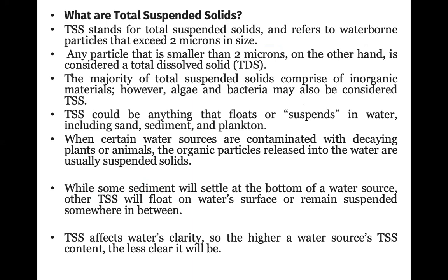Now, we can also have total suspended solids, abbreviated as TSS, and they refer to waterborne particles that exceed 2 microns in size. Here, we are saying any particle that is smaller than 2 microns is considered total dissolved solid. The majority of the total suspended solids comprise inorganic materials.